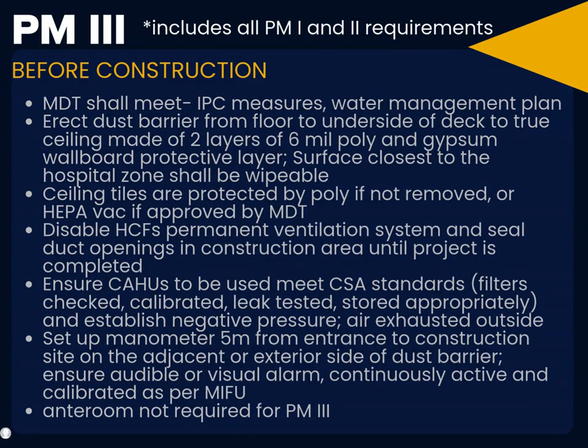For a Preventative Measure 3 project, think of something like removing flooring from a resident room in a long-term care home. Before construction, the multidisciplinary team meets to decide on the appropriate IPC measures and review any potential service disruptions. Dust barriers are set up from the floor to the underside of the deck or true ceiling using 2 layers of 6 mil poly plus a protective gypsum wallboard layer.